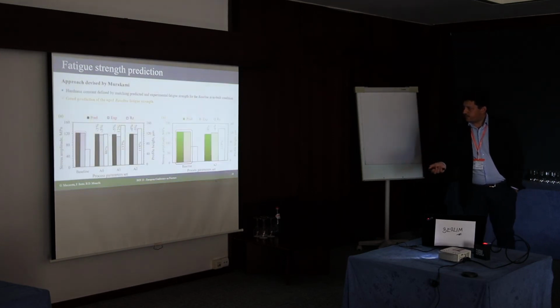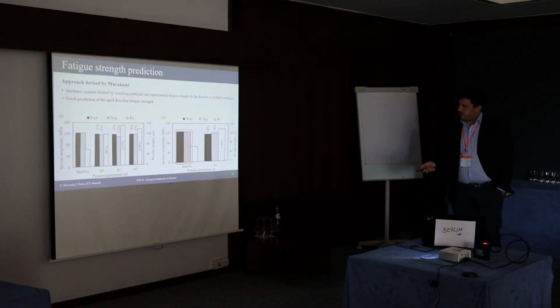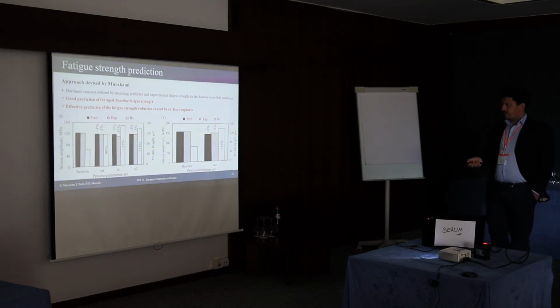What we obtained is that we found the hardness constant from the baseline condition. So these are equal due to the method, but the prediction was really good on the baseline condition. And when we see what the method predicts for the fatigue reduction for the other parameters, we see that the predictions with this approach are strongly in line with the experimental results.